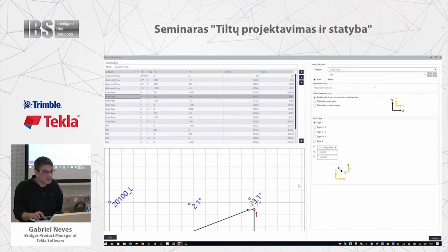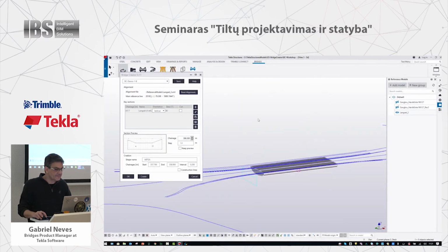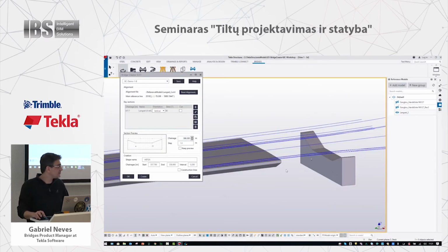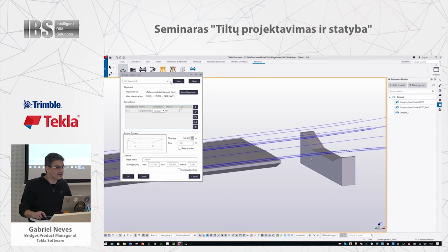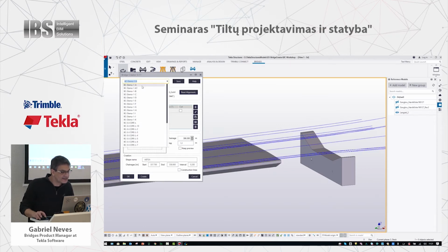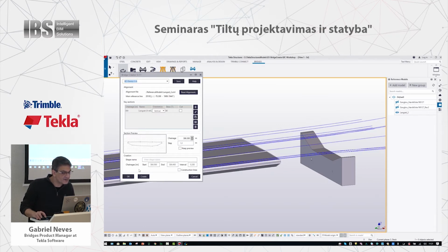And it goes 200 to the right, 450 down. So when I create that, it's in the wrong chainage because I'm playing so much with these demos. So I need to put this into the correct chainage. So I need to analyze the previous one that starts on 364.5.